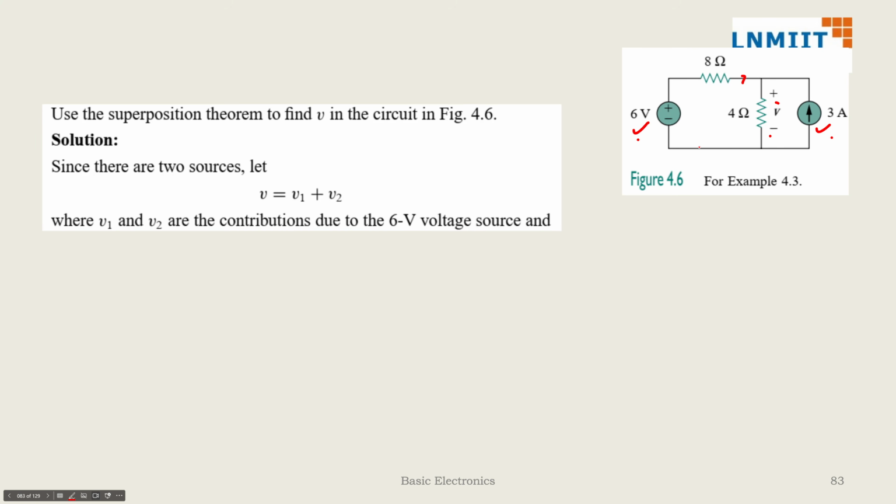So in this case we'll have to turn off all the independent sources by keeping only one alive. So turning off means replacing current sources with open circuit and voltage sources with short circuit. So this thing you have to remember, voltage source with short circuit, because zero voltage source means a short circuit will have a zero drop, and zero current means open circuit will have zero current.